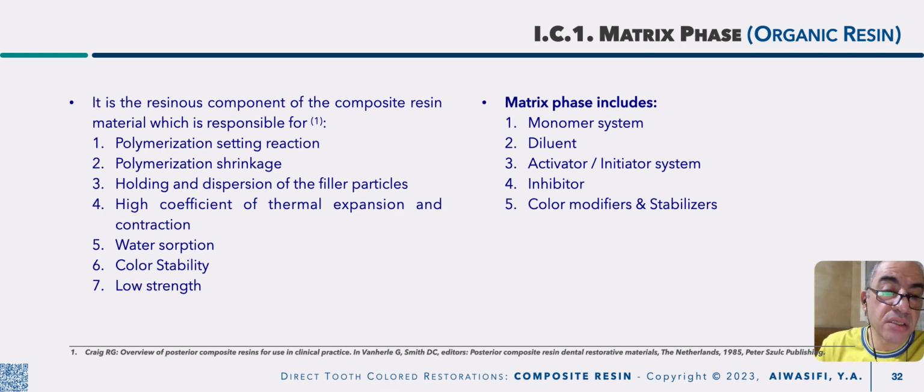That's why it is responsible for holding the dispersed phase, which is the filler. It is responsible for the high difference in coefficient of thermal expansion and contraction. It is the part which undergoes water absorption. It is the part with the color ingredients. That's why it is responsible for color stability and responsible for low strength.